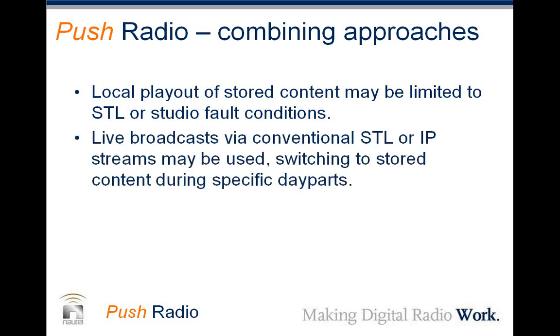Live broadcast via conventional STL or IP streams can be used, switching to stored content during specific day parts. So you can have a live show, a morning show, for instance, a morning drive show, which is sent to the station in real-time format, either via IP or conventional STL, and then you can switch to an automation running on your transmitter when that's necessary during specified day parts.